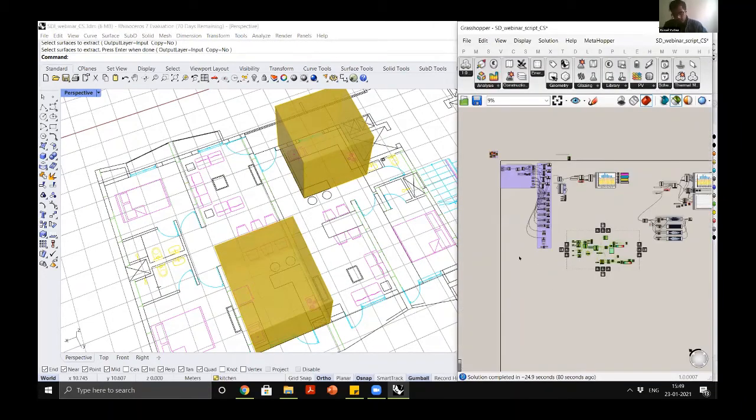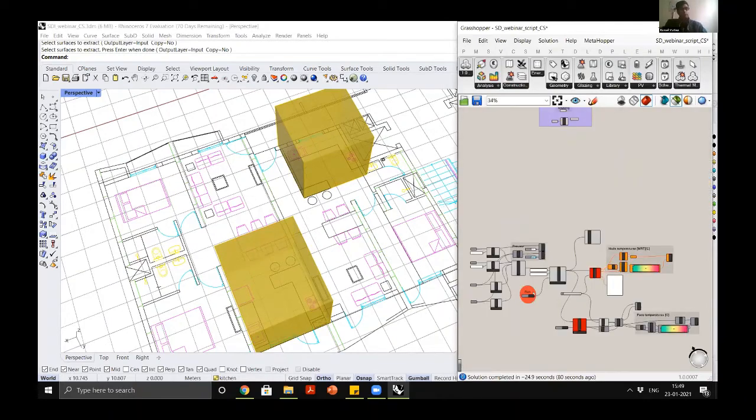It's not a very straightforward process, but for the sake of simplicity, you can compare your operative temperatures with your monthly thermal comfort band. If you're looking at, let's say, Chennai, in June, July, the thermal comfort band lies between 26 to 34 degrees Celsius. If my operative temperatures are falling between that, then I can say that my zone will be thermally comfortable.